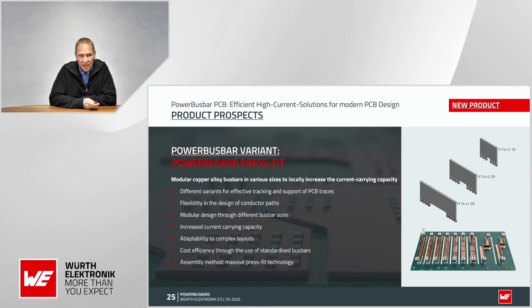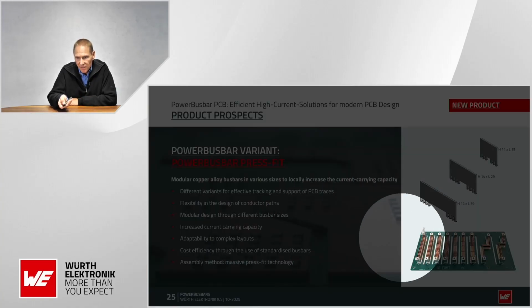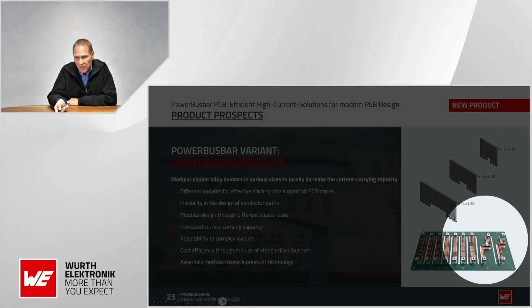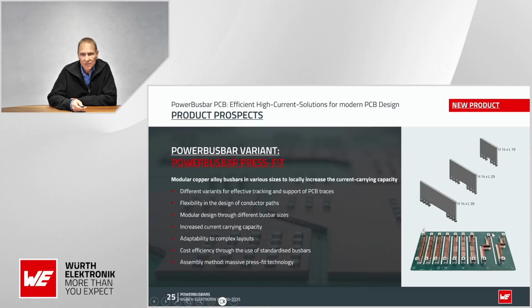These are modular bus bars with different sizes made of a special copper alloy, and are used for increasing the current carrying capacity of the PCB, but also for effective tracking and to support existing PCB traces. So you can see you reinforce the PCB traces directly.